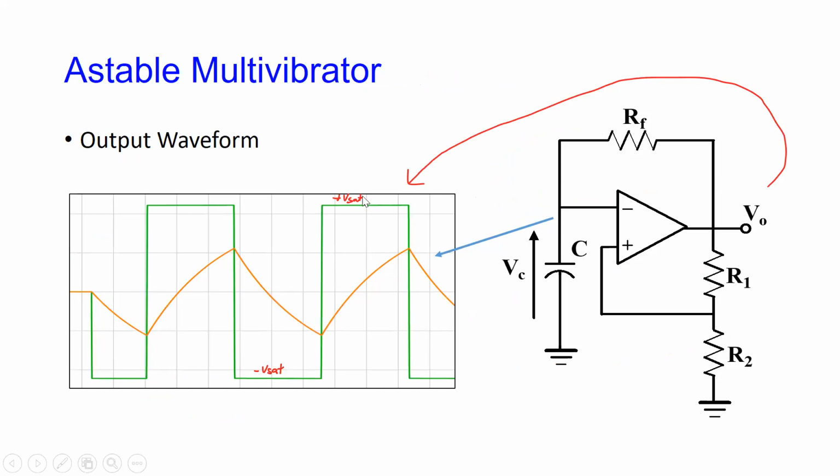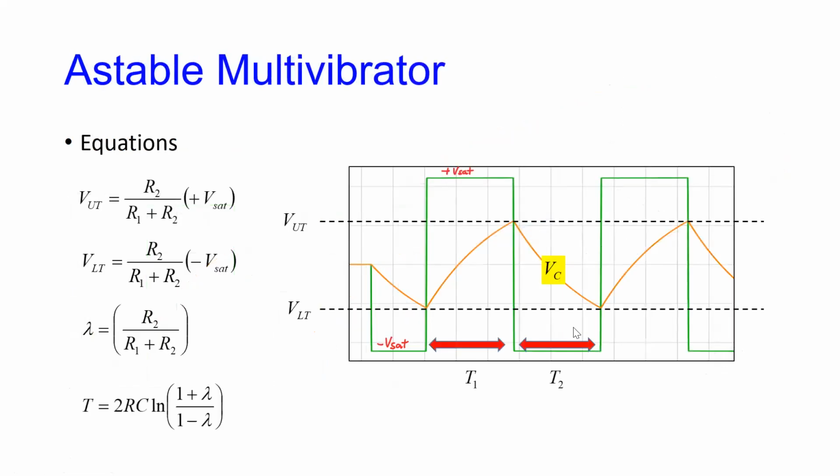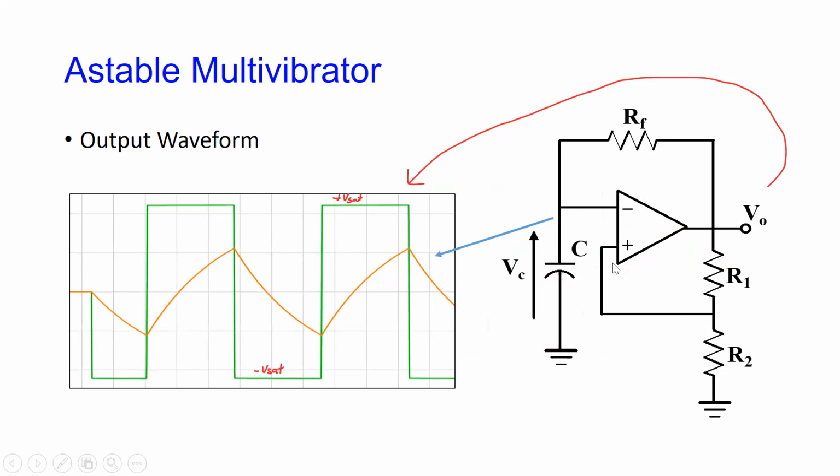The limit of this depends on the op-amp. So like if this is plus or minus 9 volts and you're using something like a conventional 741 op-amp, you will probably get this between about plus and minus 7 volts kind of thing, right? And this, of course, is the charge discharge voltage across the capacitor, right? And this is of course related to the value that you set that threshold at. That voltage is set, right? The threshold voltage here is set by this, okay?